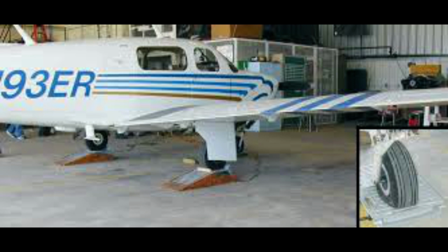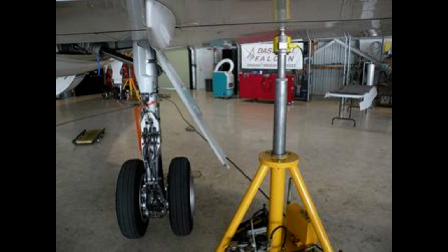3. The jacks must be straight under the jack pads before beginning to raise the aircraft. 4. All jacks must be raised simultaneously and the safety devices kept against the jack cylinder to prevent the aircraft tipping if any jack should lose pressure. Not all jacks have screw-down collars, some use drop pins or friction locks.